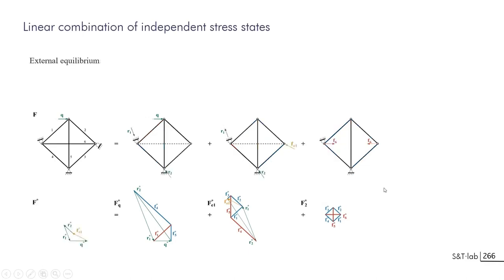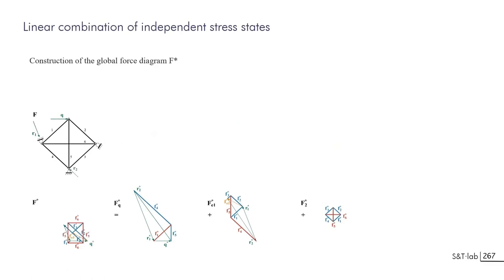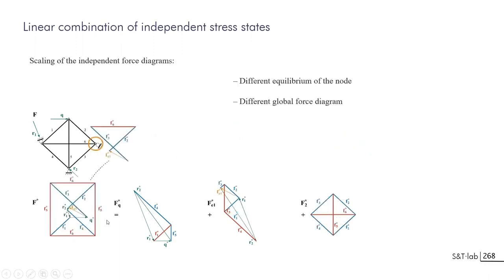And so this is quite a complicated exercise in which you can scale the different components. This is the resulting force polygon that can be scaled in different ways, leading to different results according to what is put as forces. And there is somewhere a minimum about the collapse force that has to be found if you are looking for the collapse mechanism.